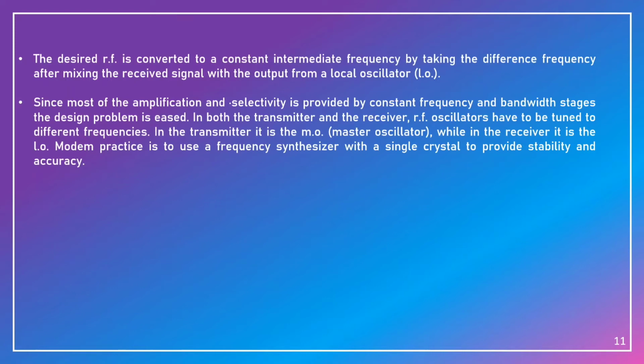In both the transmitter and receiver, RF oscillators have to be tuned to different frequencies. In the transmitter, it is the MO, master oscillator, while in the receiver it is the LO. Modern practice is to use a frequency synthesizer with a single crystal to provide stability and accuracy.